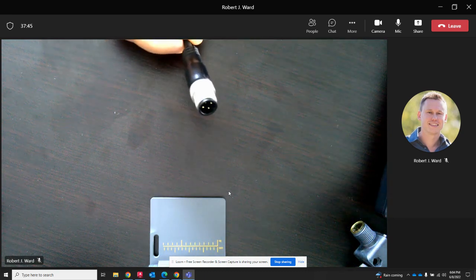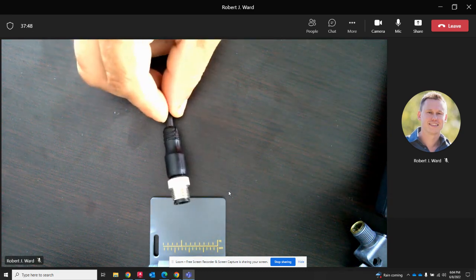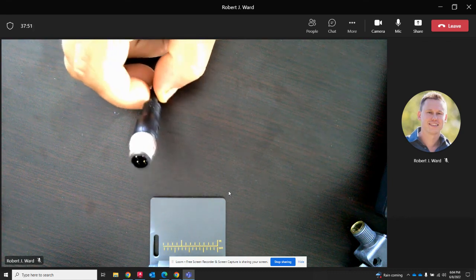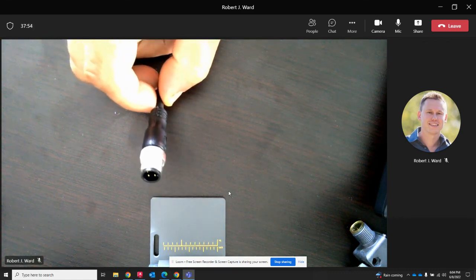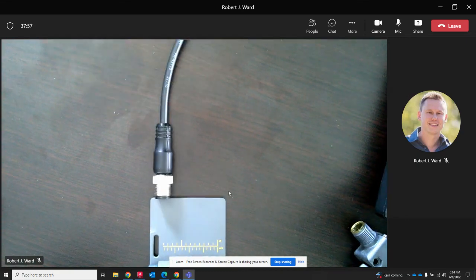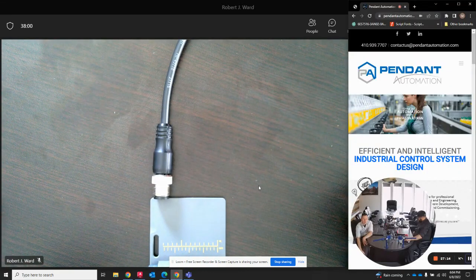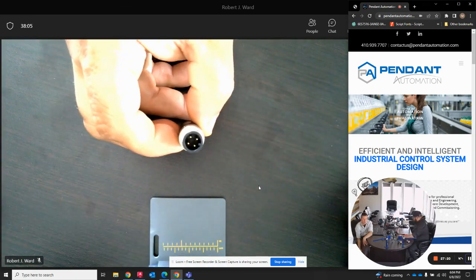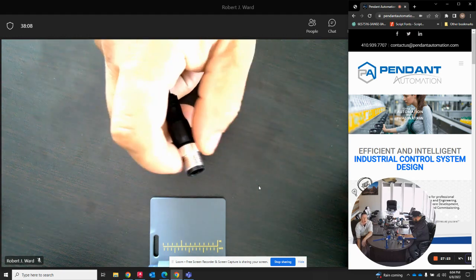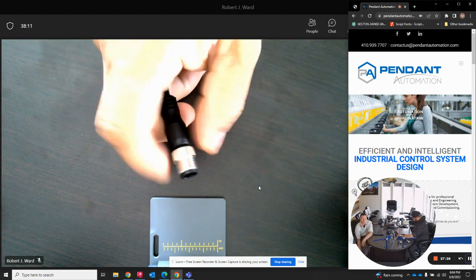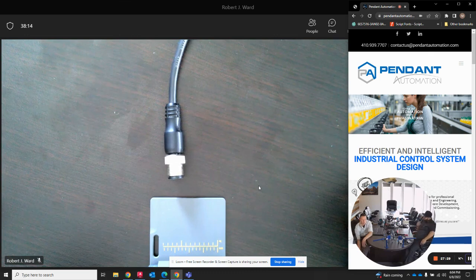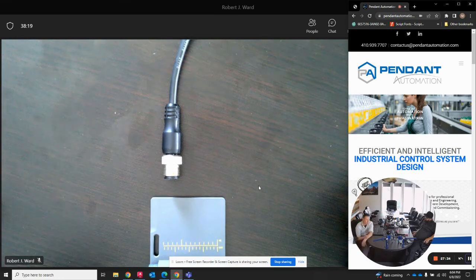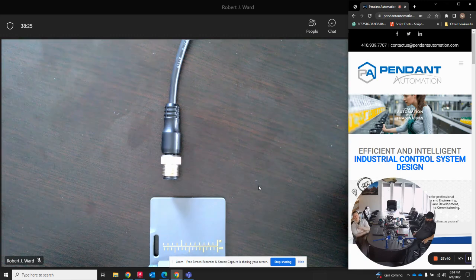I think that's one of the places that we invest in the peace of mind for the end user. So at Pendant, we often take into consideration the maintenance guy or the facilities person who's going to be left maintaining this system after we leave. We take them into consideration because this definitely is not the less expensive way to go. It is the much more expensive way to go because for every photo eye, we're providing an $8 cable. And I know that doesn't sound like a lot, but on a job where you can easily have 100 plus photo eyes, that's an extra $800 to $1,000 depending on the quantity of photo eyes.